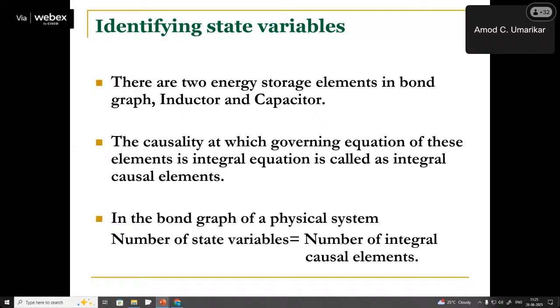Two. Because by KCL, the third inductor current will be the summation of the 2 other inductor currents, while you can obtain the state equations for only 2 inductors.